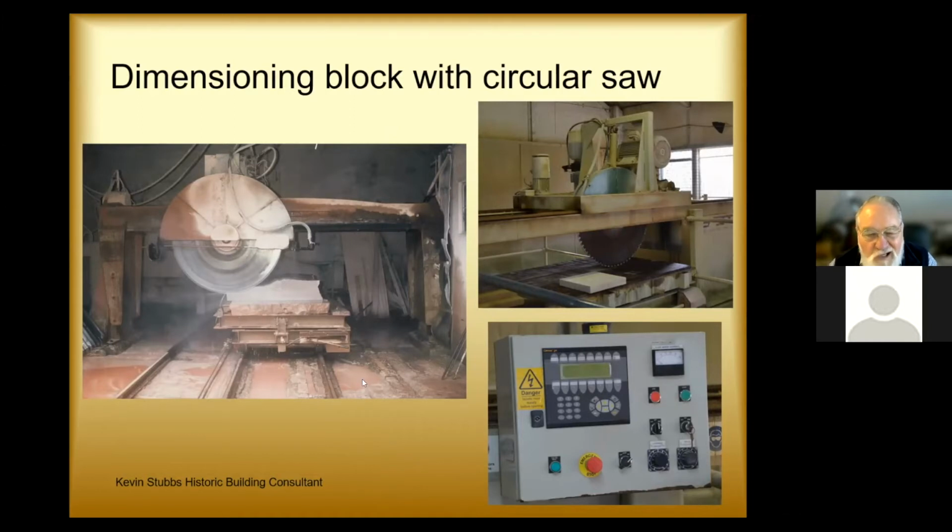So you can feed in the coordinates of the blocks that you want, set the machine running, and go and have a cup of coffee. And when you come back, you've got your block sawn. For some of the bigger jobs, they can program and use this equipment for 24 hours a day. It's running. So it's no longer the honest craftsman with his hammer and chisel chipping away for hours to create these blocks. All the primary and secondary sawing is done mechanically, and the handwork is only really for the finishing.